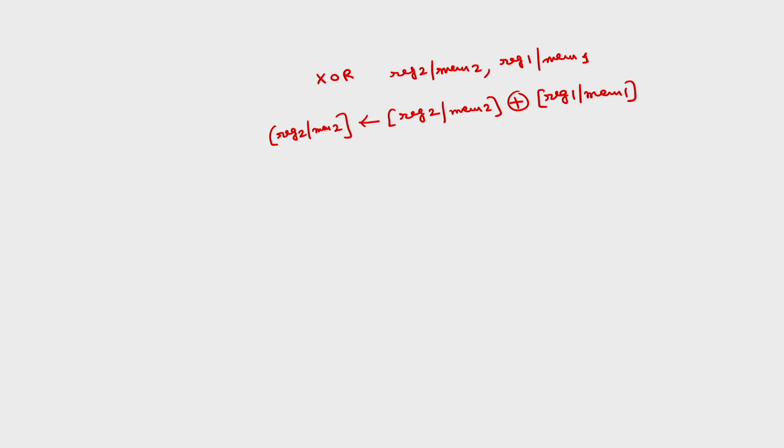There are some rotate instructions. The next group is here, rotate instructions. So, we can rotate the contents of any register or any memory location either to the right or left. We know that in digital, if I shift these contents towards the right by 1 bit position, it becomes division. If I shift the contents towards left by 1 bit position, that becomes multiplication. This is the beauty of this shift operation. So, we can shift the contents of any register or any memory towards right or towards left by any number of positions. First, we will start with a simple 1 bit rotate, RCR.